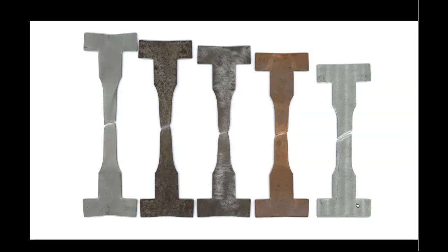Let me step back and look at the samples that you had. You had one ferrous material, and you either got a stainless steel, or annealed low carbon 1020 plain steel, or cold rolled as-processed plain steel. These samples are shown on the left in the main slide which I have. The stainless steel is the tallest. It's the most stretchy metal we have.